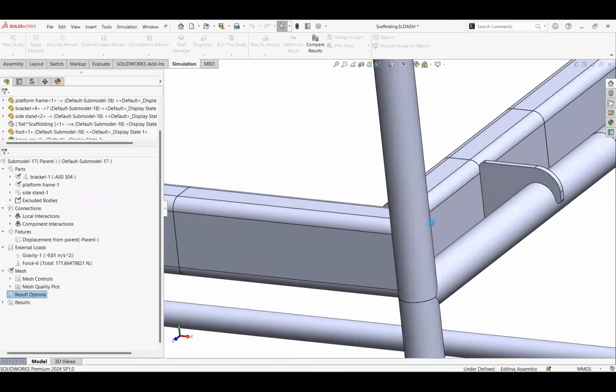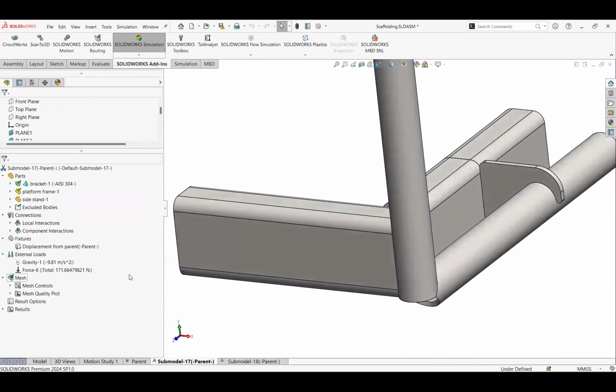So at this point, you're going to go to town, right, and apply a tighter mesh in the component of interest for me. It's going to be this bracket. And then I can look at some results and I can do some result convergence because I have a lot more resources available to me.